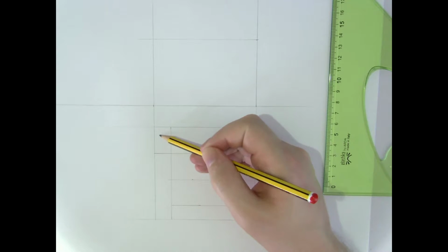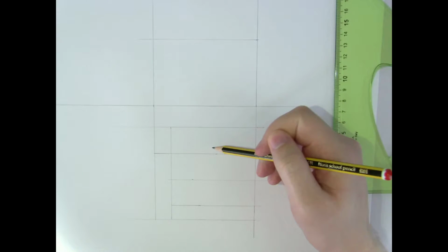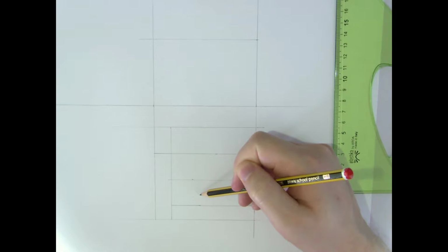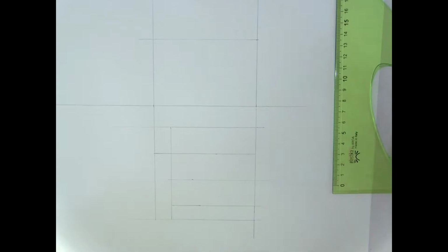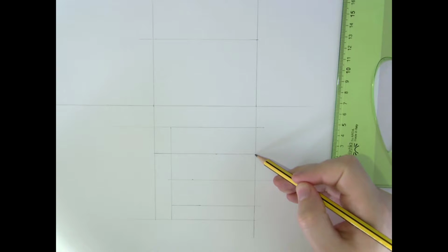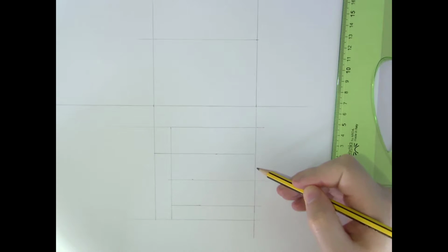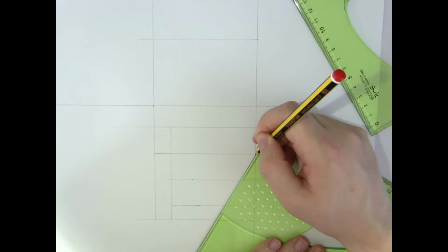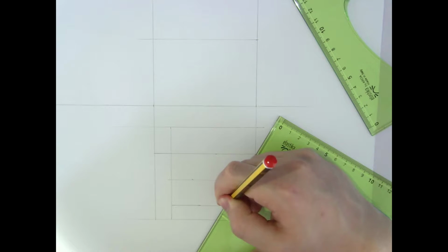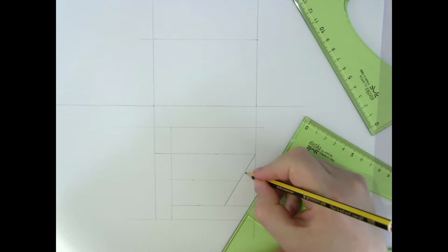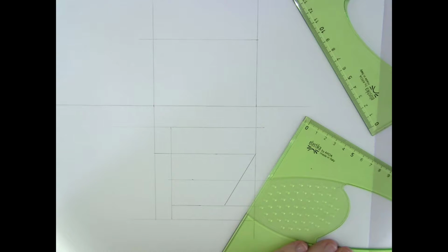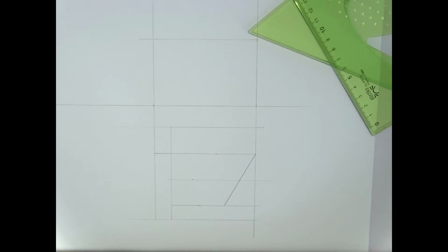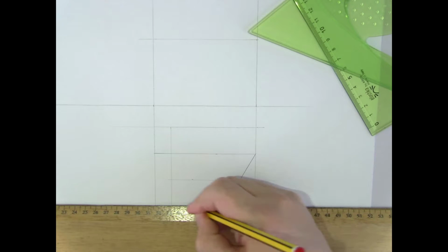So we've got the flat piece of the wall, the sloping piece of the wall, top step, middle step, bottom step, and now we must just put a sloping edge onto the side of this. So the angle that this is going to be coming off of from here is 30 degrees. So it's 30 degrees measured to here. On our set square, that would be equivalent to 60 degrees going the opposite direction. So our line is going to come down along here to the horizontal at 60 degrees and end up with 30 degrees in here for this point. With that much done, that's our surface S. We can darken in the rest of our lines.